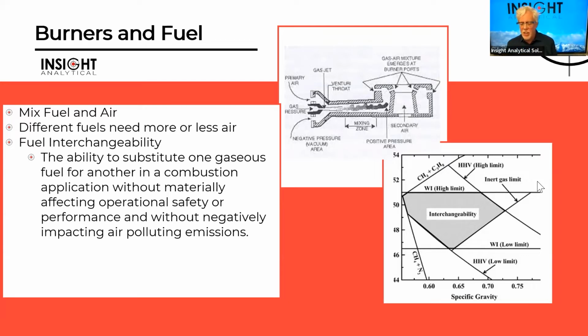When the fuel starts to have a lot of variability, when we can go from saying a methane-ethane stream to a methane-nitrogen stream, well, they have quite different air demands. They have quite different oxygen demands. And so as a result, we need to know if the fuel is changing and then make adjustments to our air to fuel ratios.